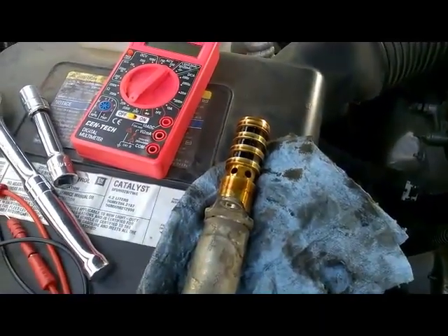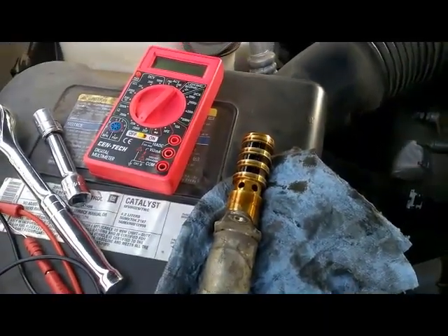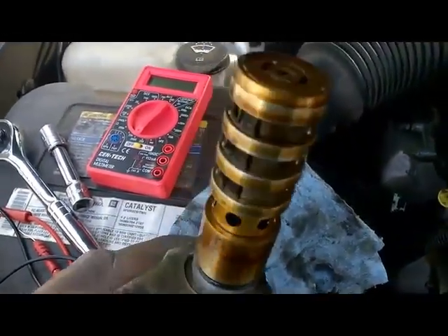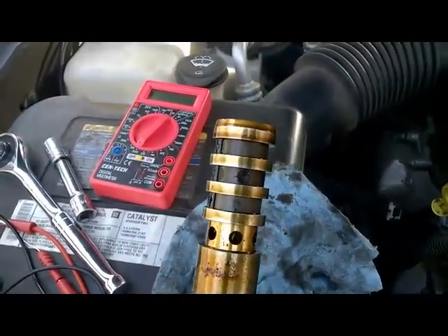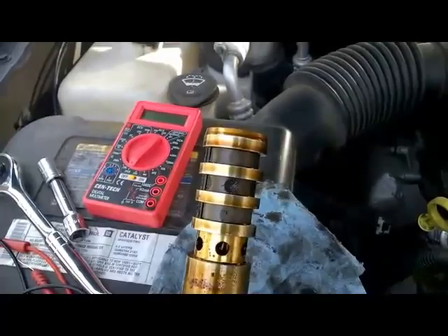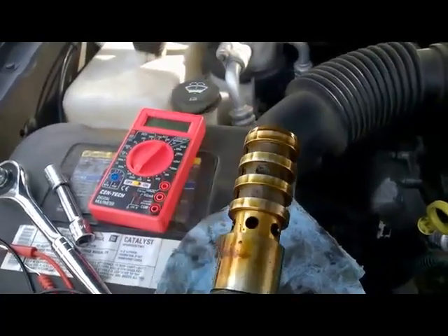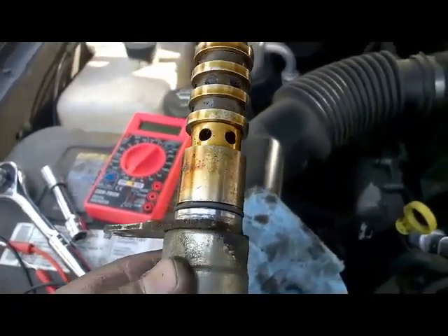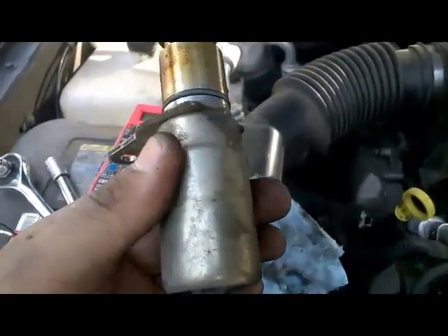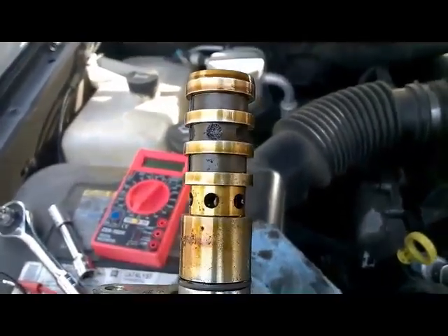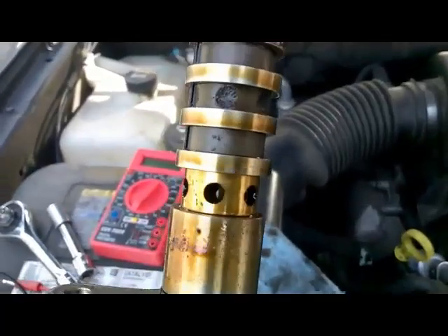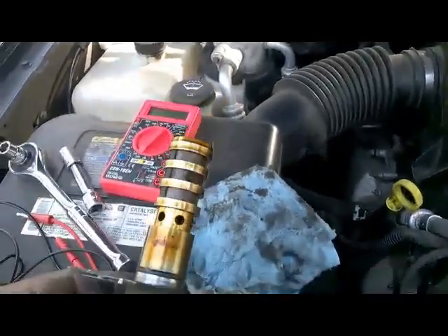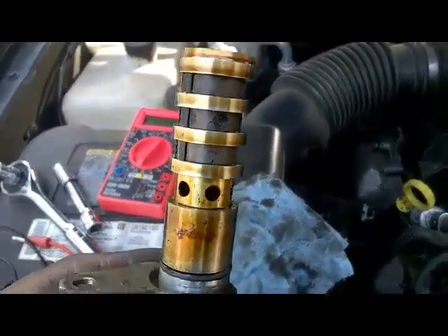And also, one more thing I wanted to add before I either replace it or clean it. It was to tell you guys that the tests that we performed, doing our voltage checks and the manual solenoid energize during engine off, or engine idling, are valid, which basically showed us that this solenoid is good, but the problem is the restricted screens for the oil passages. So that's the only info that I wanted to add.